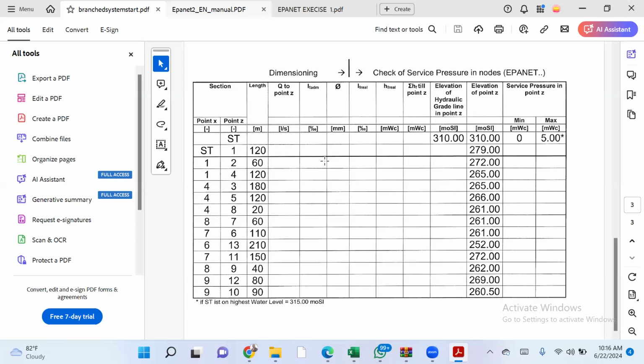And last week we said those parameters are 2 parameters for pipe and 2 parameters for the node. What are the 2 parameters for the pipe? The pipe length and the pipe diameter. You need to get it, write it down in the table format. This is your calculation sheet. If you're doing any pipe design, you must have a sheet like this. Whether it's stormwater, sewer, or potable water, or gas, there must be a sheet like this. This is your calculation sheet. This is only for 10 pipe sections. It can be up to 1,000 pipe sections. And Excel is your willing tool to do that.